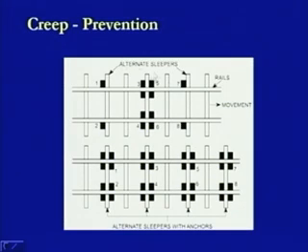Now, this is a diagram which is trying to show how the anchors can be placed. There are different ways of doing this. This is the direction of movement. One way is that we provide the anchor at this location and this location, then this alternate sleeper is left. Then further the alternate sleeper, on all the sides of the sleepers the anchors have been placed, that is one anchor has been placed here, another is being placed here. The same way it is being placed from the outer side, and if there is more creep, then obviously they have to be placed in this form,